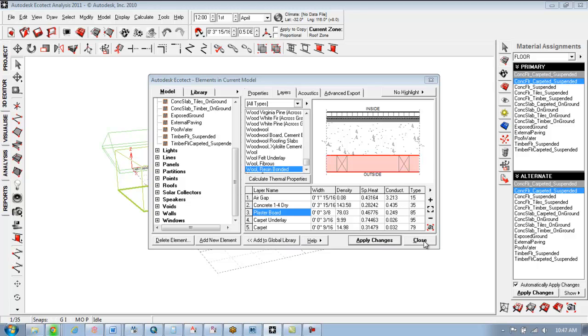But there is a very important thing: all this information is not used for Ecotect simulation. For the information for every layer, EnergyPlus just gives the total R value for the simulation. This is just used when you export to the EnergyPlus file. But for Ecotect, they just use the total R value. So if you don't want the unique layers for Ecotect, you don't have to do this.